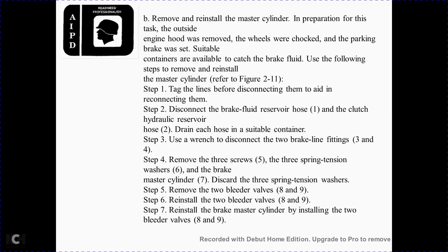Step 1, tag the lines for disconnecting, to help with reconnecting them. Step 2, disconnect the brake fluid reservoir hose 1 and the clutch hydraulic reservoir hose 2, and drain each hose into a suitable container. Step 3, with a wrench, disconnect the 2 brake line fittings 3 and 4.